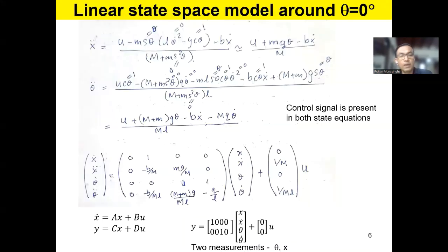Now, can we design a controller? Can we design a controller? Well, it is a bit more difficult than you initially thought because the two equations we have right now are highly nonlinear. So what we do is ask, can we linearize the plant? Okay, so how do we do that? You saw in your simulation that it was swinging almost 360 degrees, right? But if we assume that we start almost vertical, with a little deflection back and forth, but not too much, we can make certain assumptions.